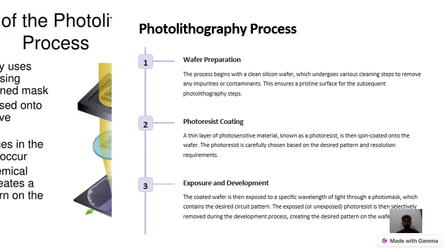Exposure and development. The coated wafer is then exposed to a specific wavelength of light through a mask that contains the desired circuit pattern. The exposed or unexposed photoresist coating is removed during the development process, creating the desired pattern.